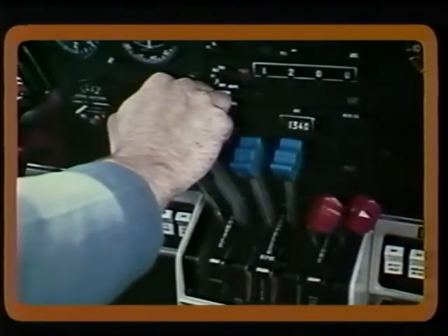For example, if a pump with a fixed orifice were used in a turbocharged system and the throttle opened suddenly, the engine would accelerate, with the fuel pressure going up before the turbocharger has time to spin up and increase air density proportionally. This will cause the engine to hesitate because of the excessive rich mixture.